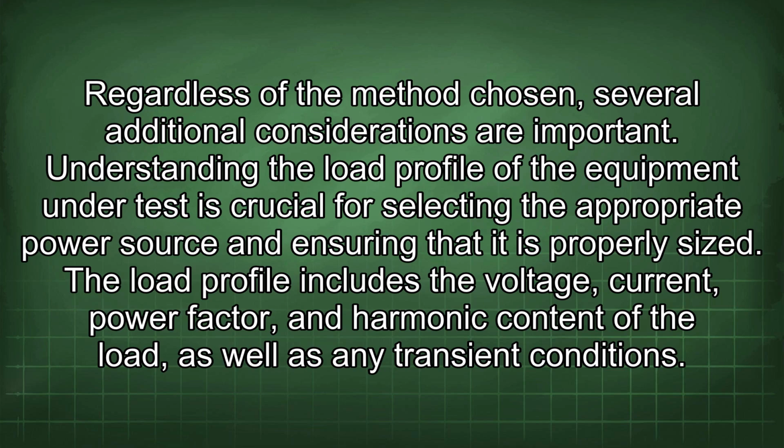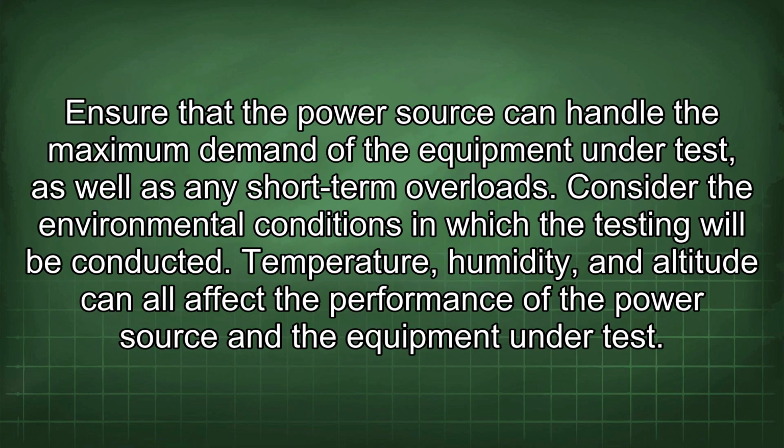Regardless of the method chosen, several additional considerations are important. Understanding the load profile of the equipment under test is crucial for selecting the appropriate power source and ensuring that it is properly sized. The load profile includes the voltage, current, power factor, and harmonic content of the load, as well as any transient conditions. Ensure that the power source can handle the maximum demand of the equipment under test, as well as any short-term overloads.